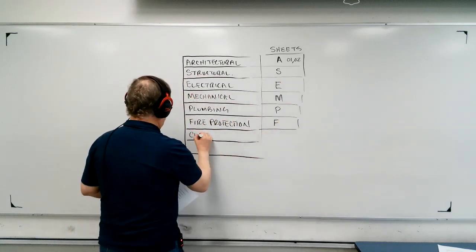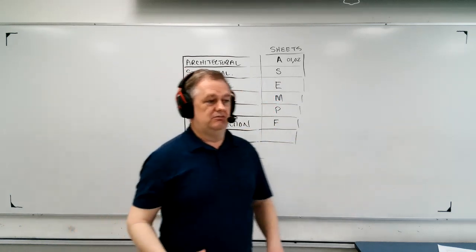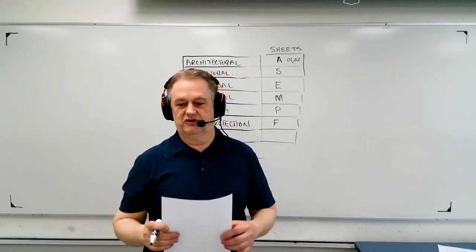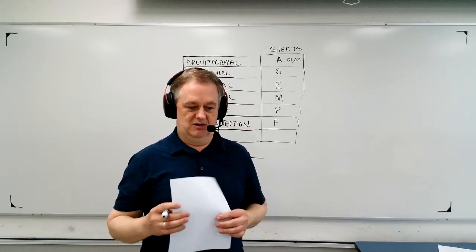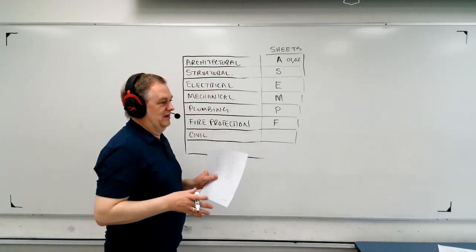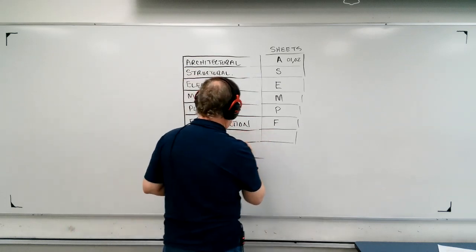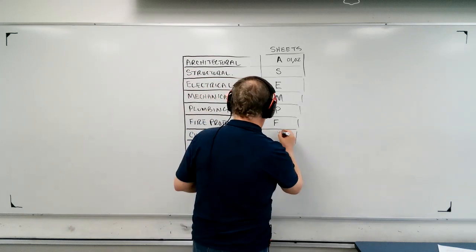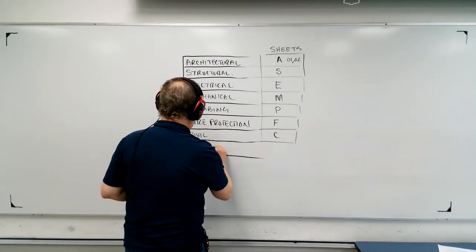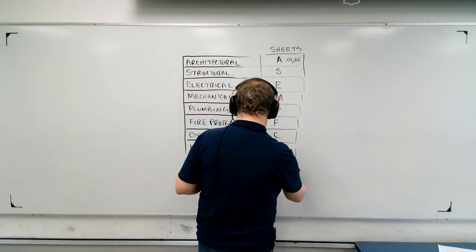Then civil. Now civil would have to do particularly with the site. So it would have to do with roads, garage entrances, and structures around the property that might be part of the project, but not really part of the actual building per se. Roadways, sidewalks, all that sort of thing, and things to do with property lines: civil, and those would be labeled with a C. And quite often, on larger projects, the landscaping would also have a set, and that would be L.